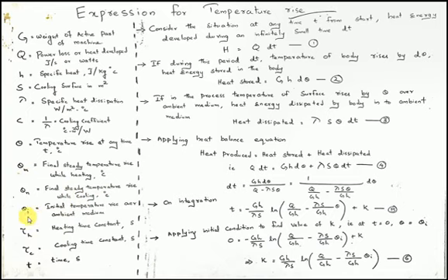Theta i is the initial temperature rise over the ambient medium. The ambient medium is actually the cooling medium which is surrounding the machine. Tau h is the heating time constant. Its unit is in seconds. And tau c is the cooling time constant. Its unit is also in seconds. And then finally we will be indicating the small t, which is time, and its unit is also in seconds.